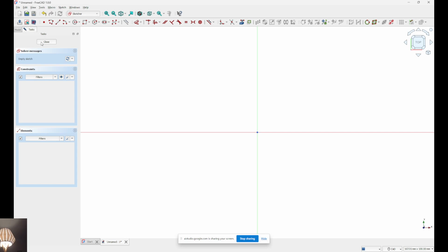Great. You've selected the XY plane and clicked OK. Now you should be in the Sketcher workbench where you can draw the 2D shape that will become your cube. Do you see the Sketcher tools on your toolbar now? I can, yes. I've got create point, create polyline, create line, arc center, create circle, create rectangle, and a bunch of others. Which one should I select?